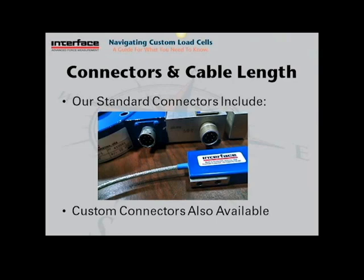All of our standard load cells come with either usually a circular Amphenol type connector or an integral cable. Our circular connectors come in both screw type or bayonet, 6, 8, or 10 pins, depending on the model. Some of our stainless steel load cells, the 2400 series, for example, have a hermetically sealed bayonet connector as a standard feature. Integral cable load cells generally come with, for a larger load cell, usually a 10-foot cable, and there's usually a 5-foot cable on our small models, our minis.